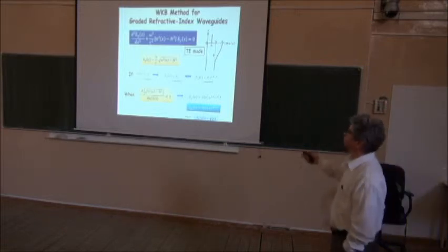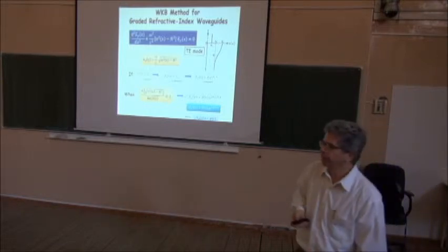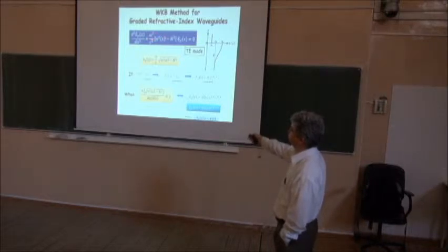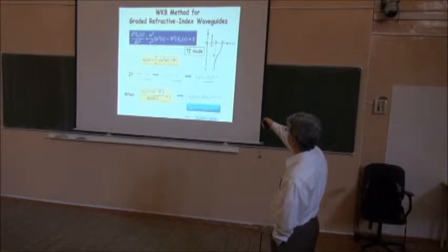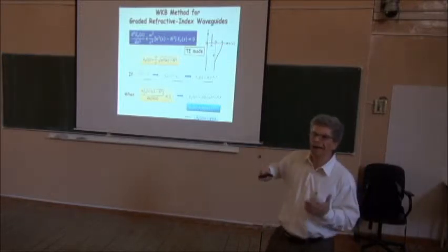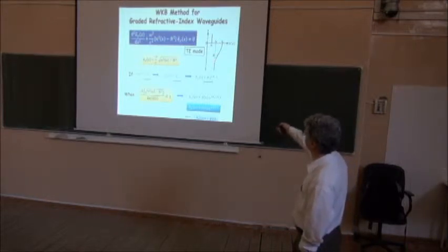And our starting point is the equation that we had, so that's the Helmholtz equation there. And the crucial part now is that we allow this refractive index to vary. And going back to our coordinate system, we're going to take a case that we have a cladding here that has a constant refractive index. In the typical case, we have a piece of glass or lithium niobate that we have a little increment on the refractive index close to the surface.